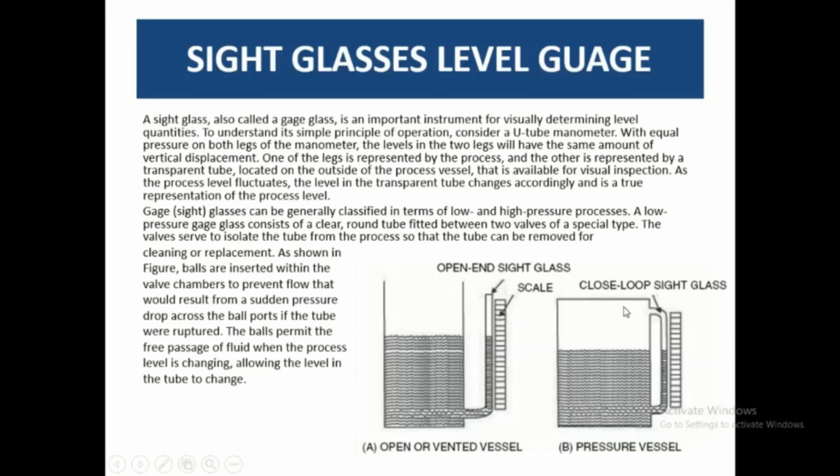On the other hand, if I talk about the closed tank, either it is pressurized maybe, or maybe under vacuum. In both scenarios you will get different results, because if the process here is under vacuum, and that part you have just left open to the atmosphere, again this value will deviate a lot, because here the pressure will be much higher.